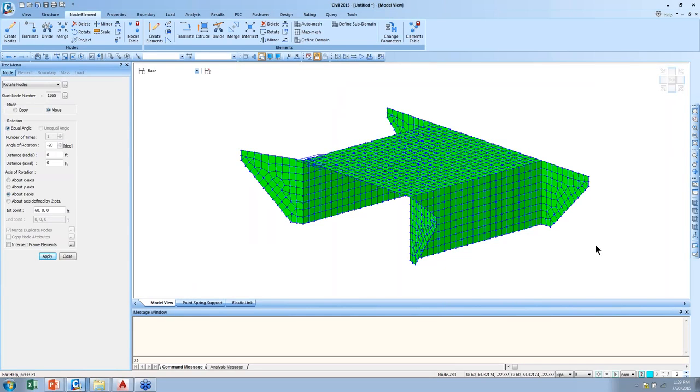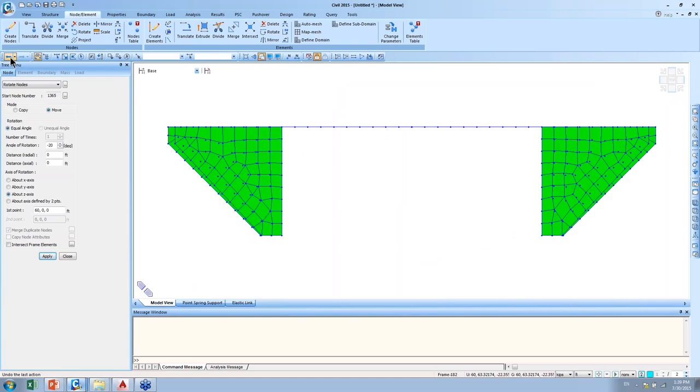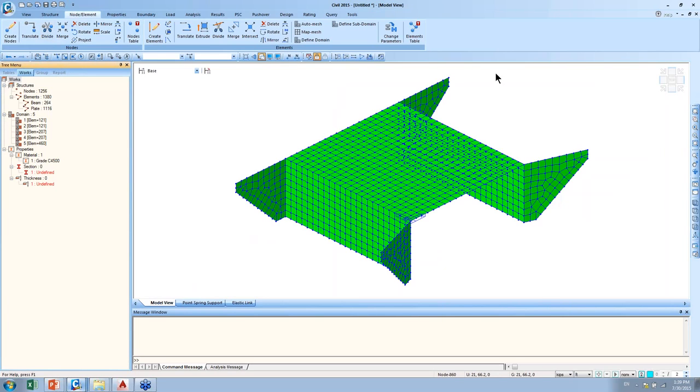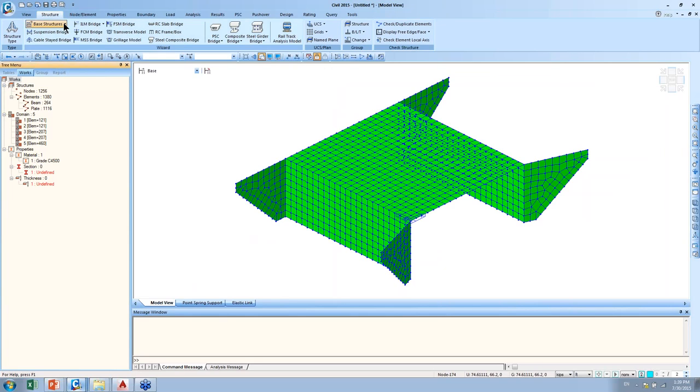Okay. For this, I'm going to create, really quickly, a very simple model. Actually, I'll leave it as it is. So let's say from this structure, we want to reflect the top curve for the slab. What you can do is go to the Structure main menu, go to the base structures, and find a bunch of the basic wizards. So Structure main menu, base structures, and arch.